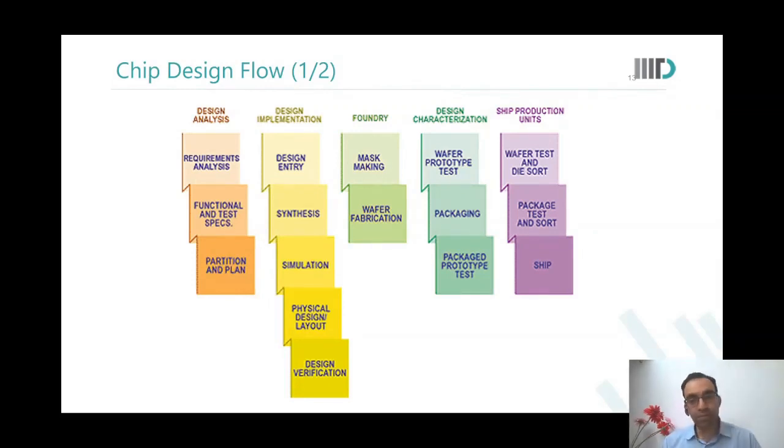The design verification that I have put on this slide over here at the bottom of the design implementation stage is exhaustive. It includes simulation-based verification, includes stages like DRC, LVS, ERC checks, everything. Package verification, everything is done in this stage. Only after everything is fine, you send something for mask making. Okay, and so we are also including the formal verification and those kind of things. Yeah, we will look at that in the next slide because that is too much detail.